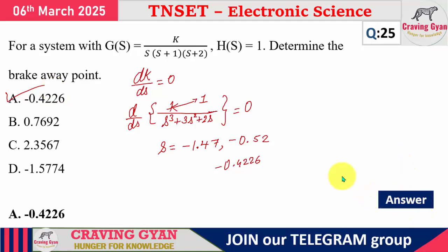Option A is correct. Always, a breakaway point should lie on the root locus. The pole locations are at the origin, at minus 1 and at minus 2. In the region between 0 and minus 1, you will have the root locus, because placing a point there, on the right side there is only one pole or zero, an odd number, so the root locus exists. Between minus 1 and minus 2, no root locus exists, but the inverse root locus exists. Important.